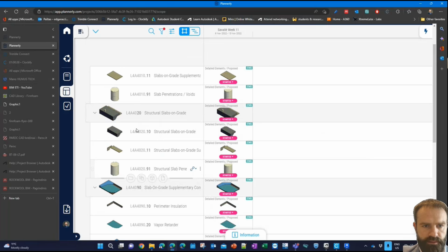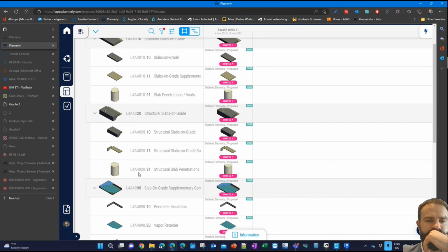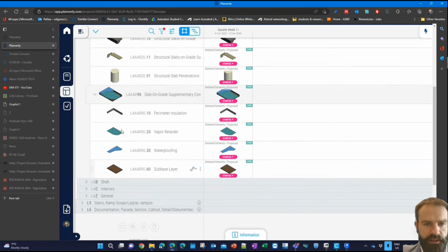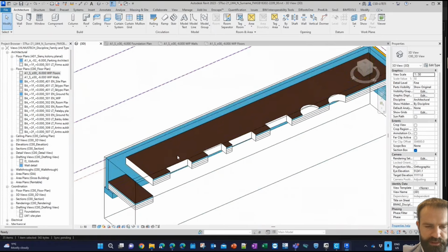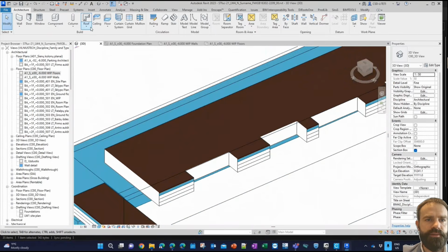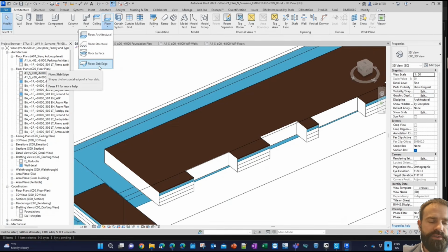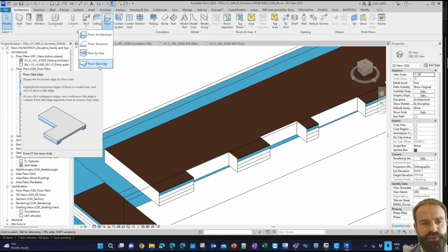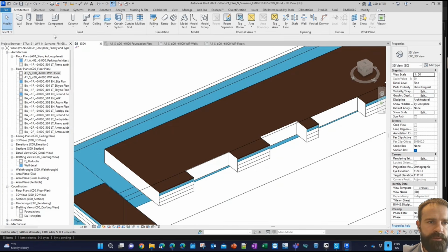Okay, layers, openings, slab edges, and perimeter insulation or perimeter reveals. So for these elements, you can go, I think, inside. For perimeter insulation, also slab edge can be used. You can just change the position and the size of slab edge and use it as a perimeter insulation.